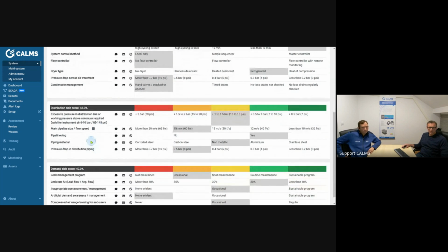Right. Then on the distribution side, I see also that you have a serious problem. I will put on a red tag because you obviously have a problem on one end. Yes. Pressure drop is the biggest problem. Yeah, that's our problem. Yes, put it here on the red. The size of the main header pipe is well designed, so it's 4-inch. The main is 4, and then down is 3-inch. So in the main, everything is okay. It should not be a problem.